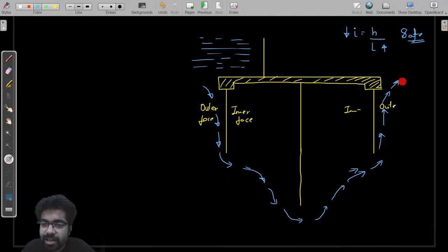He observed that soil erosion started from downstream, and slowly and slowly, as we have already discussed yesterday, the pipe or tunnel gets completed towards the upstream side. And when this pipe is completed, then obviously water will immediately rush in. Okay, are you getting the point?